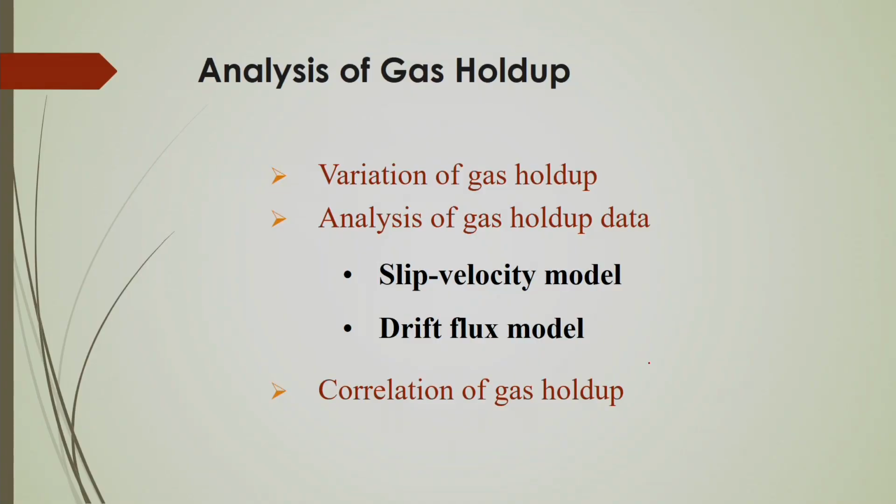Now, how to analyze this gas hold up? Whenever you are measuring this gas hold up, you will see there will be a different effect of parameters, the effect of variables, on this gas hold up. Maybe this gas hold up will be changing with respect to the nozzle diameter. This gas hold up will be changing with respect to the physical properties of the system.